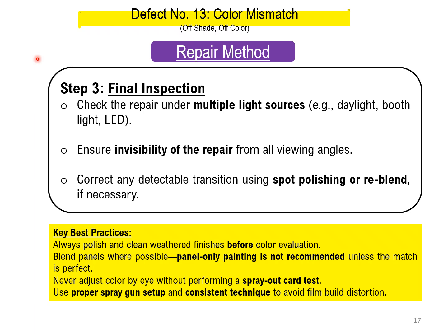After completion, go ahead for final inspection. Check the repair area under multiple light sources. Ensure invisibility of the repair from all viewing angles. Correct any detectable transition using spot finishing or reblend if necessary.